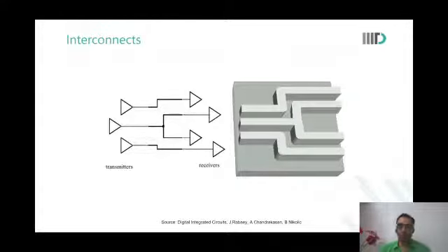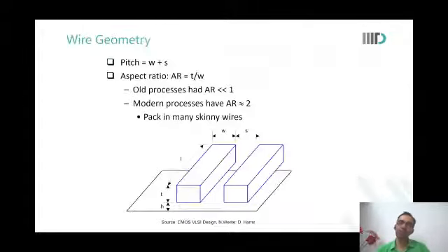In advanced technologies, all fabs use copper. In earlier technologies, let us say 180 nanometer and older, people used aluminium because the copper process was not as defined yet. However, today you will also find technologies which use 180 nanometers with copper. These are hybrid technologies to gain density or to have more current carrying capability. Copper is more ductile than aluminium, and therefore these wires can be drawn very close to each other.